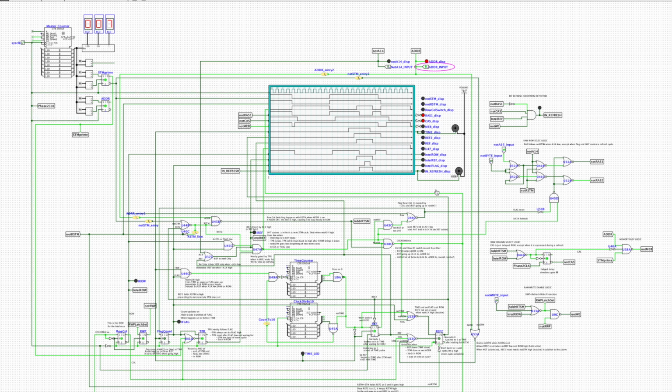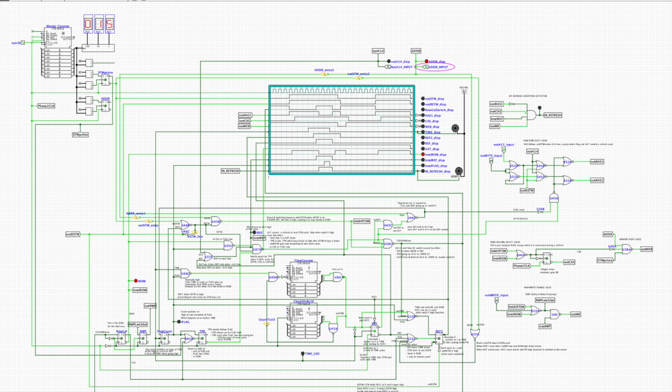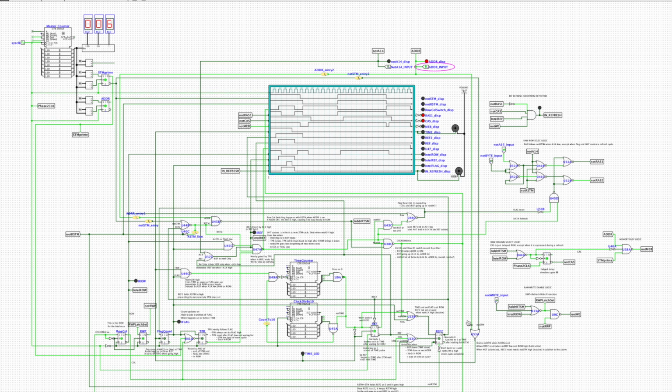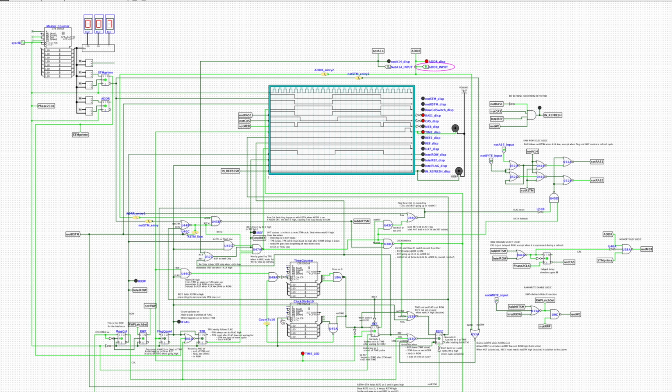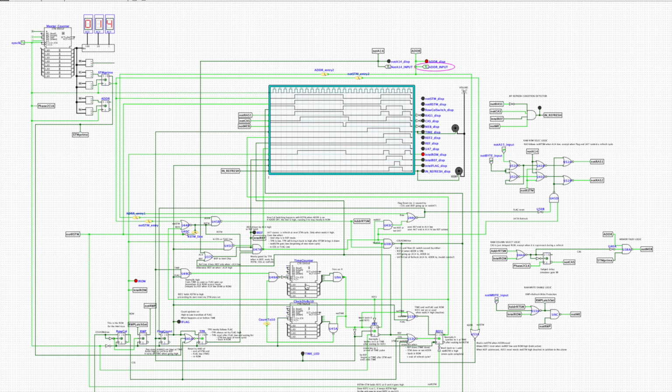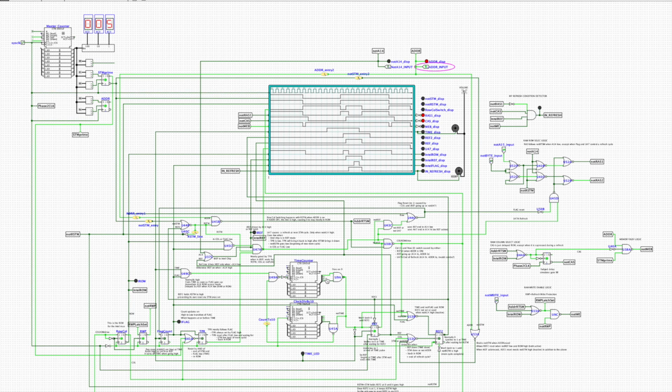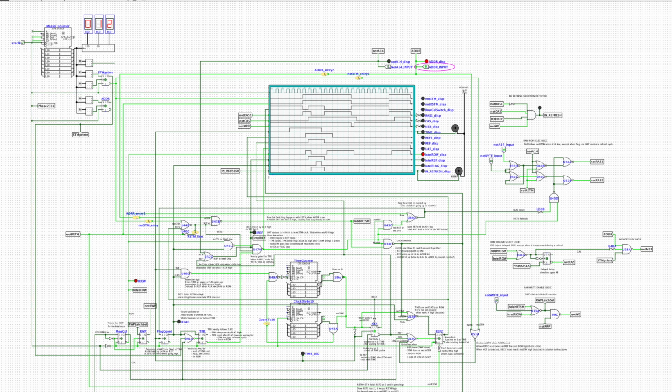The one that didn't simplify at all was this here, which is the control for the 2 signals, the refresh, which is that little light here, and you find it over here somewhere, Intel refresh, that exposes the Intel refresh counter, and the flag, which is actually the same as count. It updates the counter. So to do those two, you have this incredibly complicated logic, which is driven by a timer in the middle. So if you follow the clock here, it's directly driving this, which is a divide by 10. And you have another divide by 10, so it's a divide by 100, but already you can see that it's in a snake loop that eats itself.